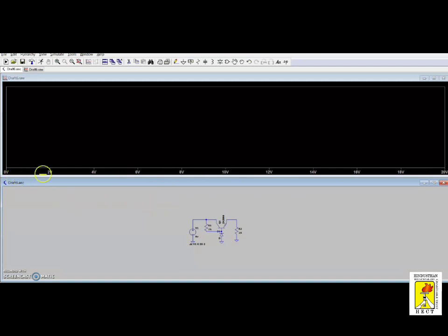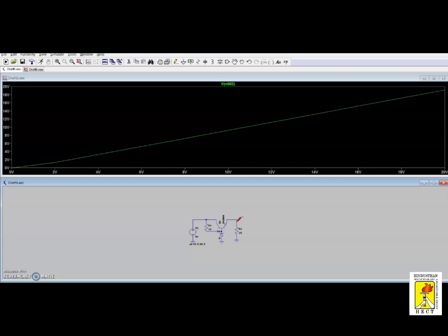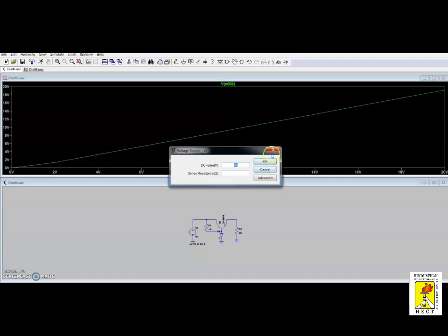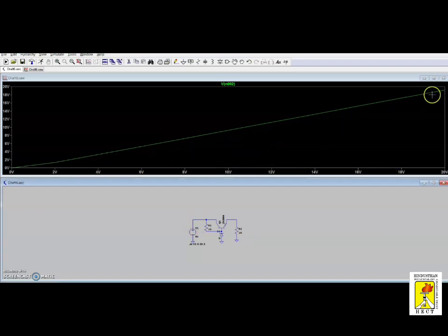This is the input voltage: 0 volt, 2 volt, 4 volt, 6 volt, 8 volt, 10 volt. Now you measure the output voltage and you can see how it is varying, by keeping RL, that is the load resistance, constant at 1 kilo ohm. So this is line regulation. It gets a linear rise, and it is going to get stable at nearly 19 volt.